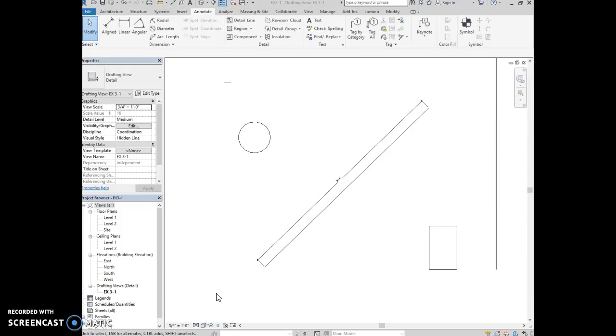You can use Object Snaps in two ways: normal mode and temporary override mode. Normal snap mode is a feature that constantly scans the area near your cursor when Revit is looking for these inputs. You can configure which types of points to look for. Using a temporary override Object Snap will allow you to pick individual points quickly. So let's take a look at an overview of the Snap dialog box.